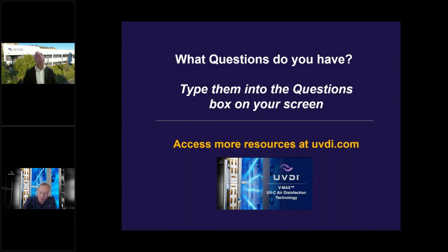These are the ones I'm familiar with today. ASHRAE 241 has a standard, it doesn't have a standard. They refer to the standards which I just mentioned, the ones which are published, but that was before 185.3 was published. So now that 185.3 is out there, that could be used to measure the effectiveness of air cleaning systems in a room.